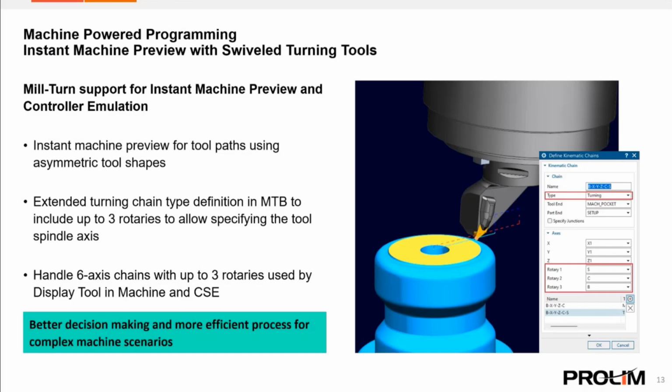So this specific feature concentrates on support for auxiliary spindle axes as used in the chains of lathe machines, and certain mill turns contain both the tool spindle and a workpiece spindle. In such a case, there can be three rotary axes between the tool and the part. As a chain definition only has two rotary axes, this capability enables the system to solve for the necessary value of a third rotary axis. So enough of me talking through the slide.